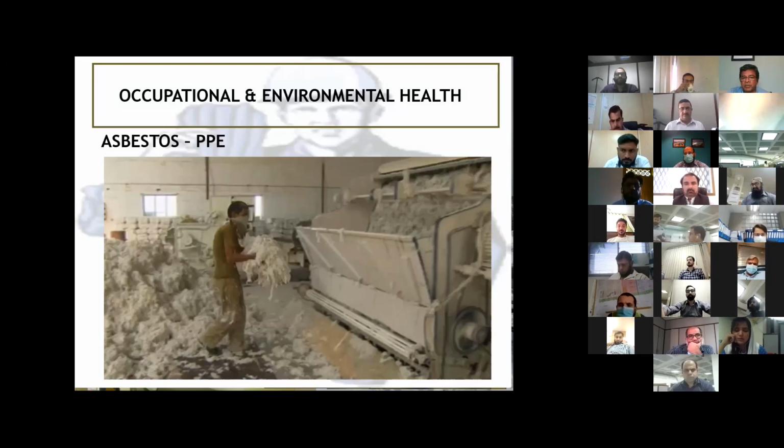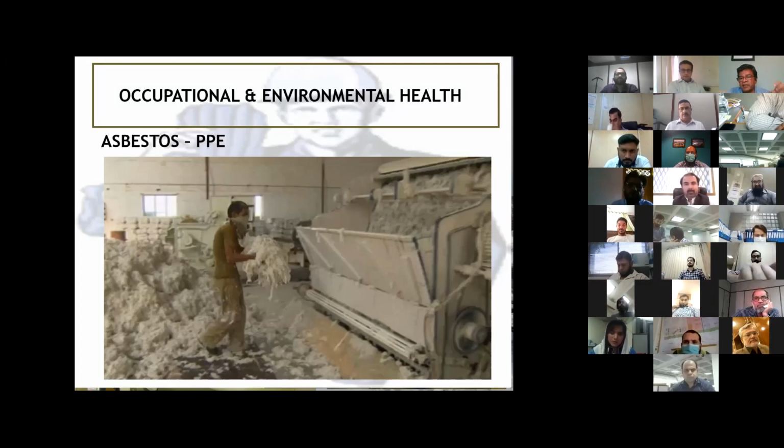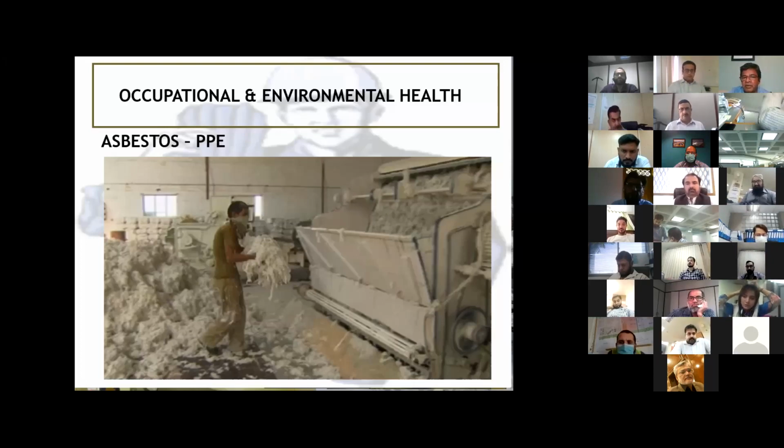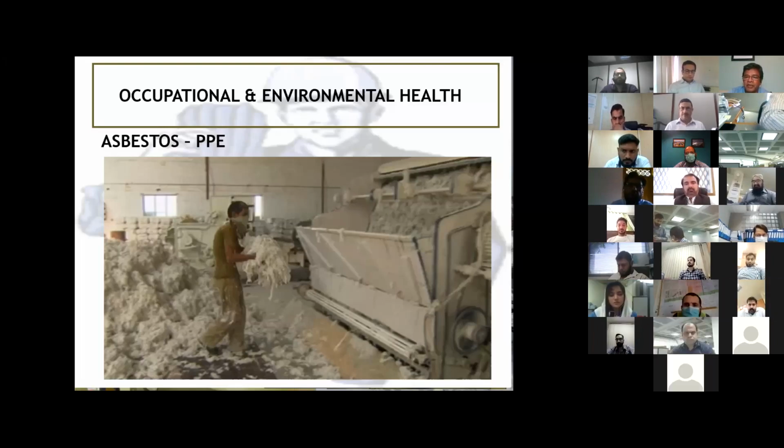This is that raw asbestos, in some cases crushed to use in floor tiles or plaster. But I showed you that removed fireproofing, it's exactly the same thing when removed. When they apply it, they put some bonding material and water and they spray. But when you remove it, it looks exactly like this, just fluffy, cotton-like material. But this worker, I can't comment on what he's doing or what kind of protection his owners or supervisors have given him.